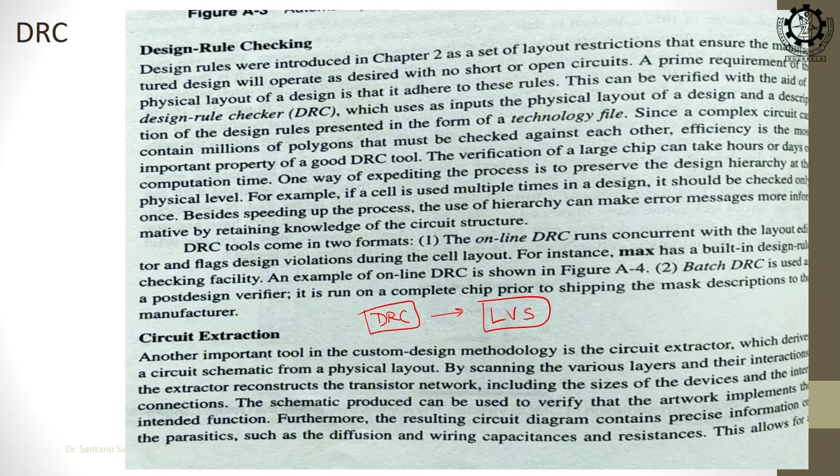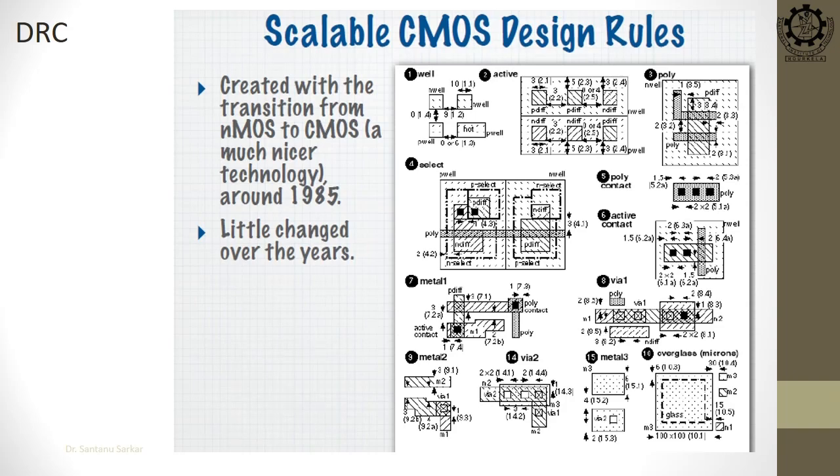So, in case of digital design, all these layouts are automated, but in case of analog design, most of the time it is hand drawn, because in analog your number of transistors is less, but the circuit can ask for higher linearity and careful matching. So, generally all the analog layout is hand drawn, but because in digital circuits your number of transistors is so large, you manually cannot do it. So, we get the help of the tools.